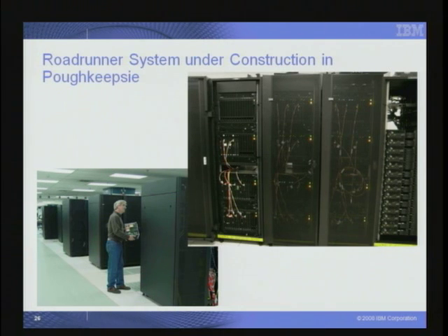But since you're talking about across technologies, let me just say that our studies show it to be increasing some. The error rate per unit area as you go from 130 nanometer down to 65 is getting worse, but it's not stunningly worse because things are getting thinner in addition to getting smaller. So the answer is maybe yes, maybe no, but I see you're working with Los Alamos too, so I'll talk to you about that later.